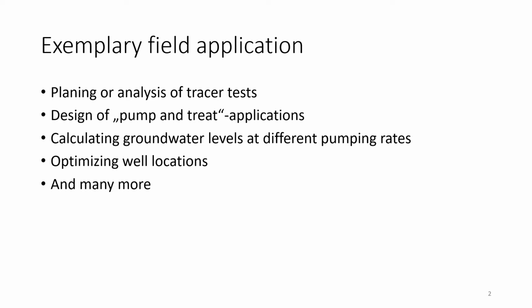Also, the planning of pump and treat applications is a good example for numerical simulation. You have some kind of contaminant in the subsurface, you want to pump it out, treat it on the surface and re-inject the clean water. Then you can simulate, for example, optimal pump positions and pumping rates in a numerical model.